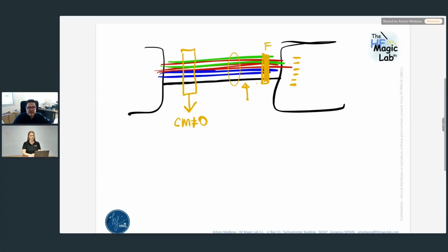It is the same. In a USB bus, you have your signals. You are interested in not distorting the differential signal, the data, and you introduce the common mode choke to introduce impedance for the common mode, while being invisible to your signal. You have very nice application notes on the Würth Elektronik website, where you can find how to introduce common mode chokes in the USB signals, introducing additionally some kind of protection like TVS diodes to avoid ESD problems in immunity. So go to this application note. If not, let me know and I can look for the application notes for you on the website. But it's the same idea.